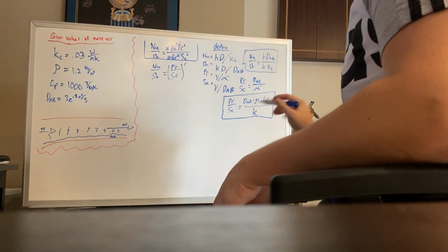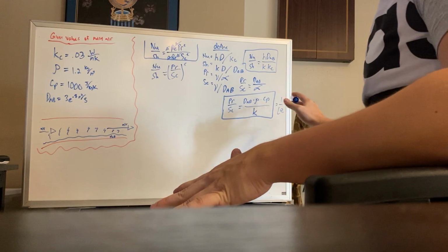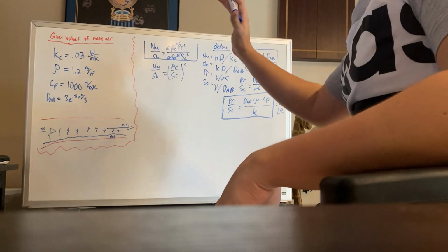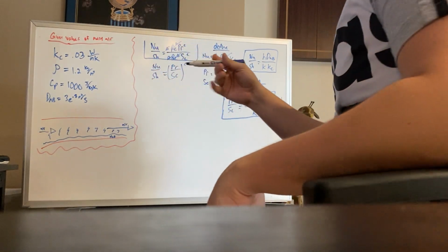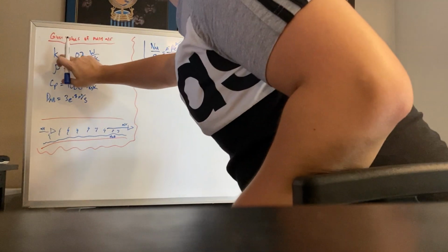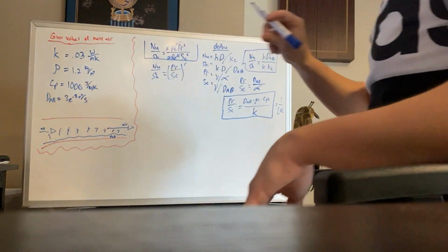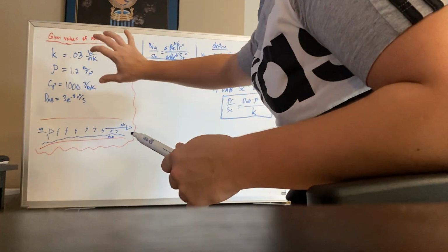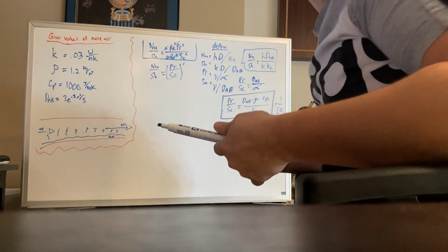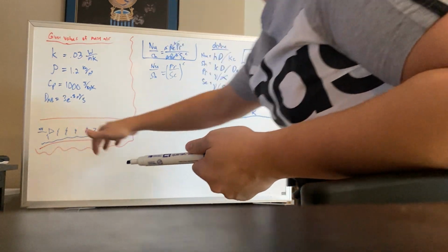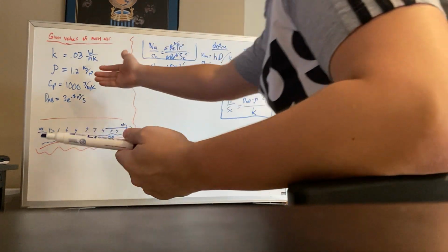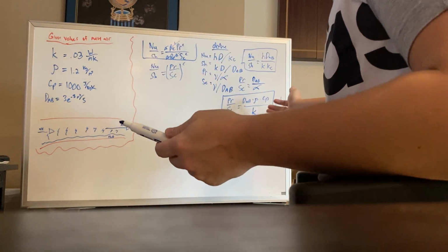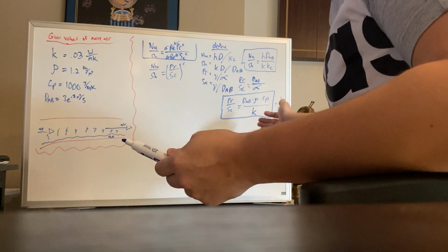But first off, before we look into that, we have the numbers over here. I just realized this is not supposed to be the mass transfer coefficient. That's a heat transfer coefficient, my apologies. But so we can look at these, and these are values that are given to us from moist air content. Since we know that some of this water is going to be evaporating up into the air as it travels through the pipe, we can just go ahead and assume these numbers. And this will help us in trying to estimate what we should be setting the right side of the equation equal to.